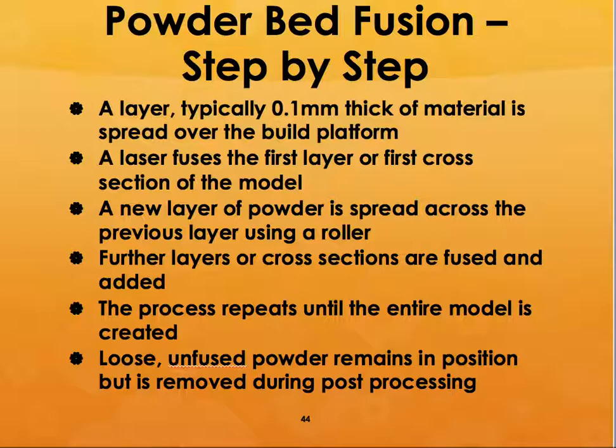So essentially you are depositing one layer, and then you use a roller to spread that powder, and then you melt it or partially melt it or sinter it to fuse the parts together. Then the process is repeated until the entire model is created. And then at the end, you have loose unfused powder. In this technique, you really don't use any kind of support material, because the powder bed itself is used as the support material for this technique.